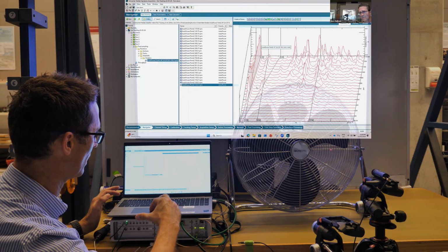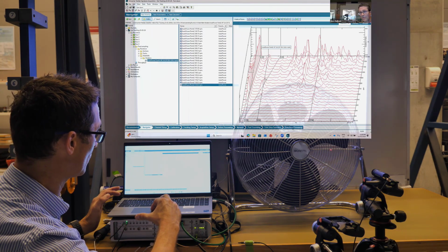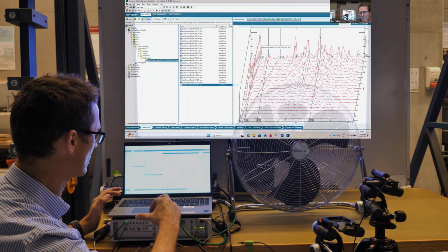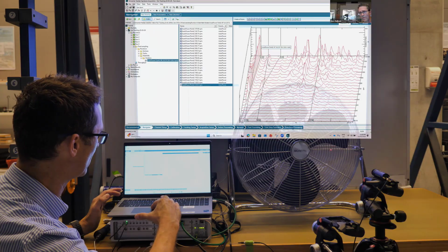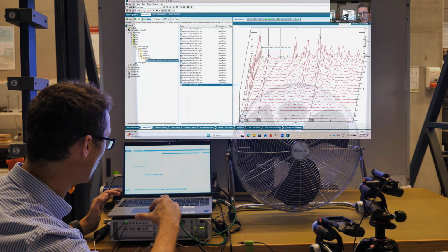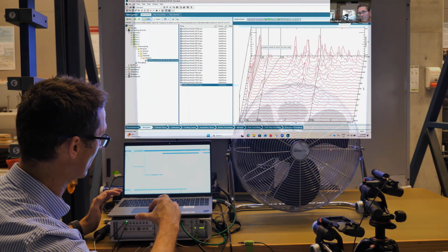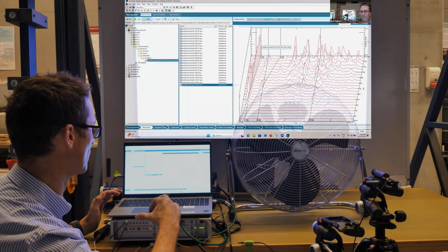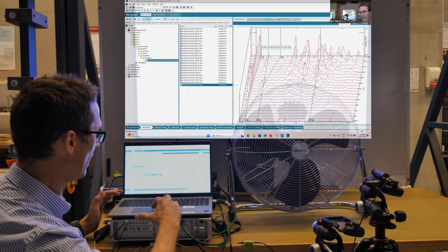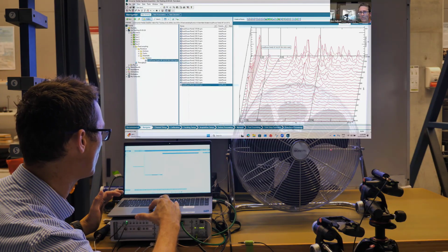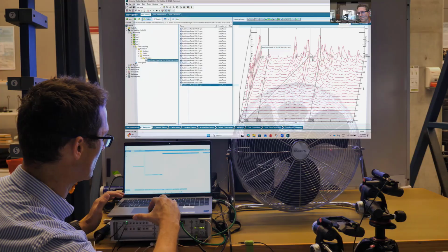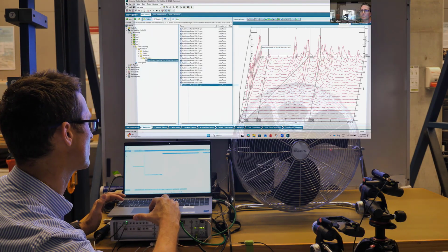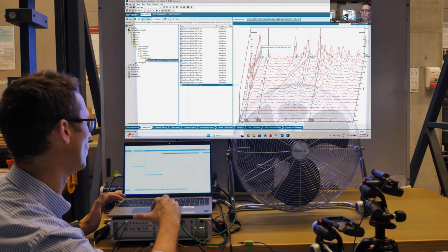You can see similarly for the third order, when that coincides with this particular natural frequency at 38.3 hertz, I get some higher order peaks. And again, at the top here is where the second order coincides with 38.3 hertz. And over here, similarly, if I was to open this up perhaps to 6th order, we'd start to see some of the interactions even with this 153 hertz resonant frequency at these higher orders.